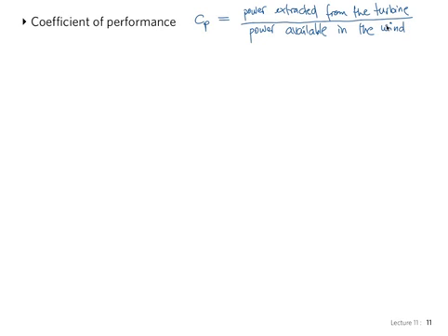So the turbine extracts an amount of power from the wind, and we've already calculated that. But how much power was already available in the wind? Basically, the full kinetic energy of the wind, if it had gone to full stop, is how much energy was there, right? But it didn't go to full stop. It went from 10 meters per second to 7 meters per second.